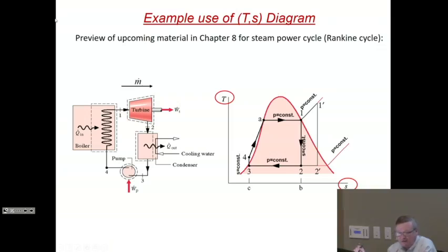Now we could make that into an ideal Carnot cycle. If we started from the vapor here, we condense it partially. We then would put it in the cooling water condenser, this instrument, but we would stop when it's here, and then we would pump it straight up. That would then be a Carnot cycle, because the pump really is, in this case, an isentropic machine. It's kind of idealized, but let's just say that's what it is for the moment.